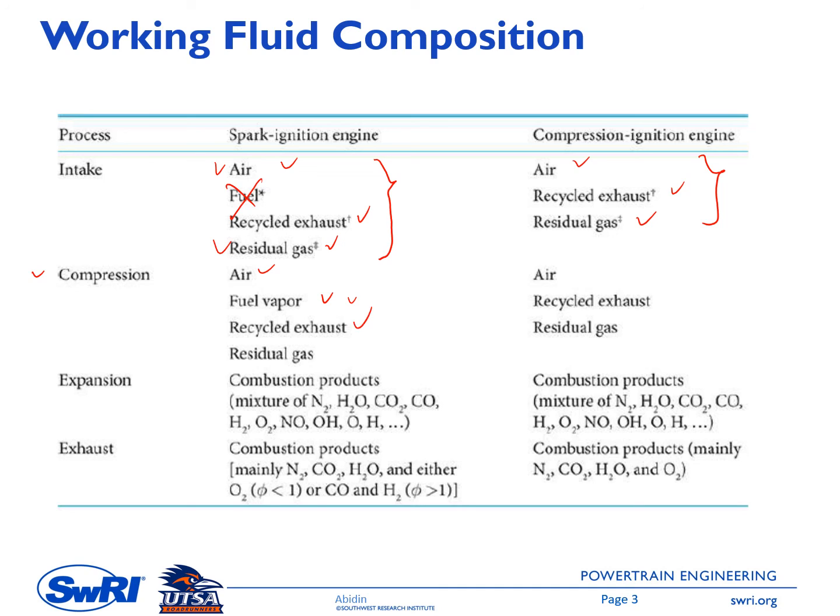Same thing, we might have recycled exhaust and residual gas. In the diesel engine, we have air, we might have recycled exhaust, and we have residual gas. For the diesel engine, the fuel is introduced at the end of the compression stroke.